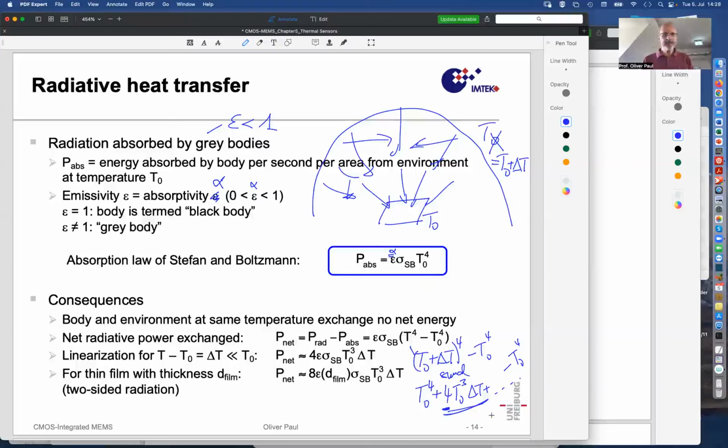And then you can also think about these thin structures that we have also seen are essential components of many thermal sensors by their fabrication, because they need to be insulated so that they can really transduce any energy changes, maximum the temperature change. Thin structures, then, we have, of course, emission in 2 directions, and we can have 2 surfaces emitting in 2 directions, and therefore there is a factor of 8 here.